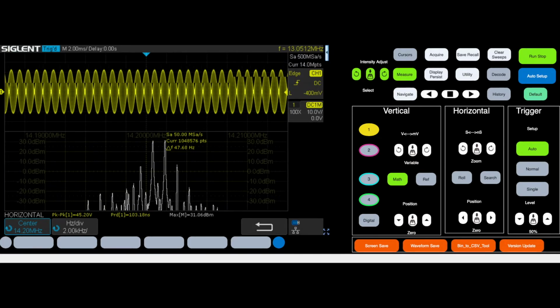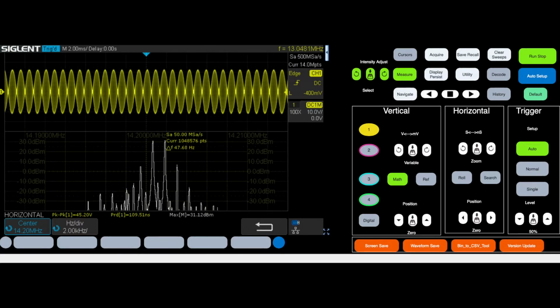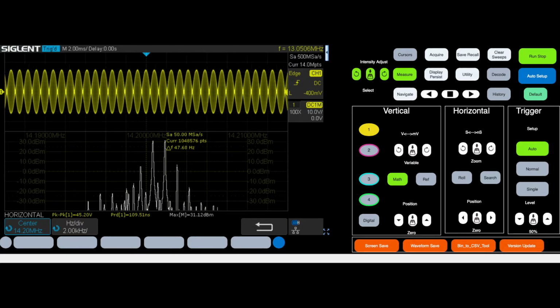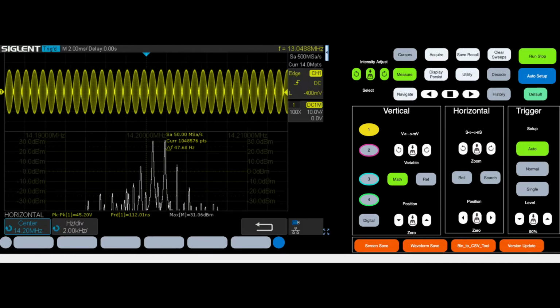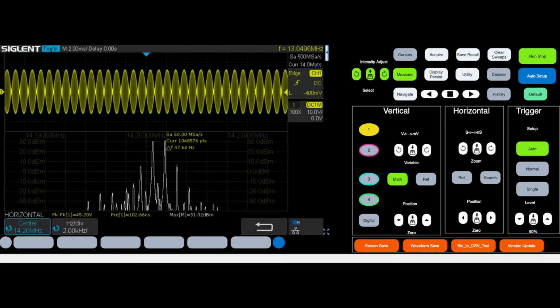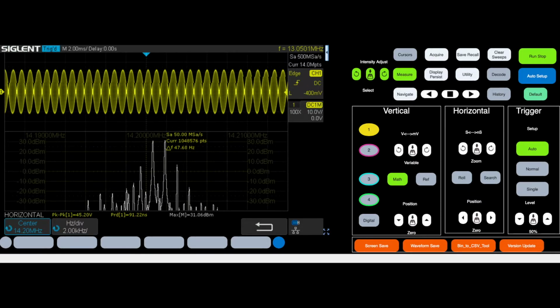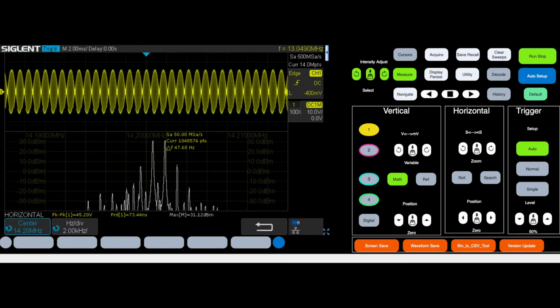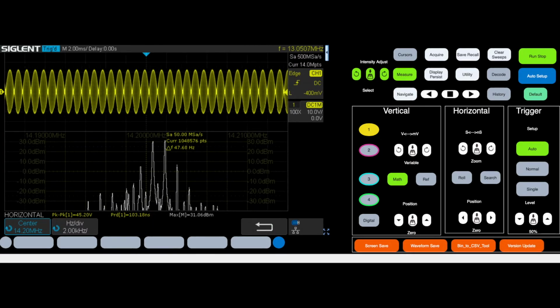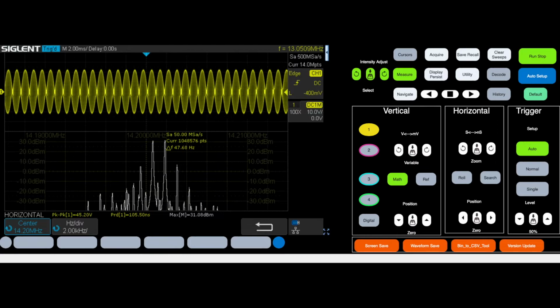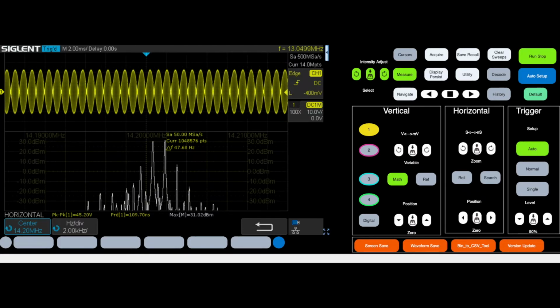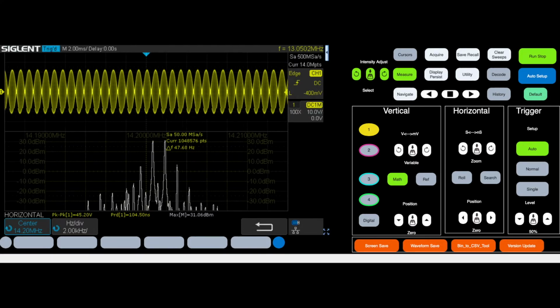An intermodulation distortion measurement shows the spurious products generated when we put two signals within the normal transmitted passband into a transmitter. And they are being displayed here, and we can now measure them using the graticule and other tools that the oscilloscope provides.